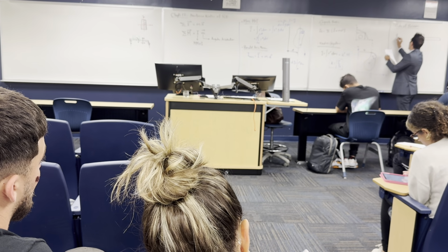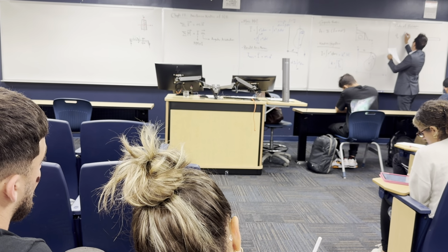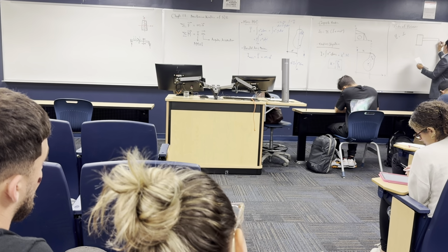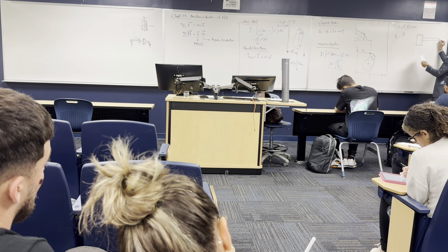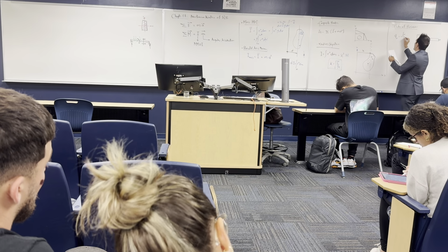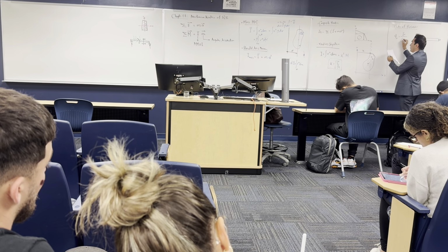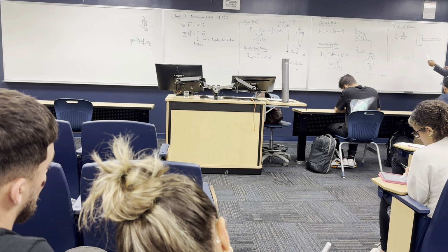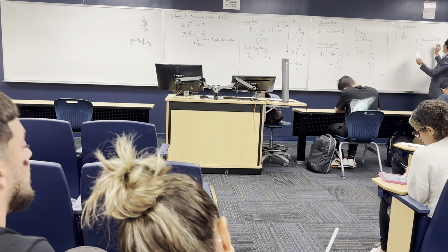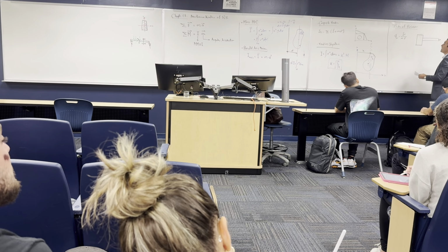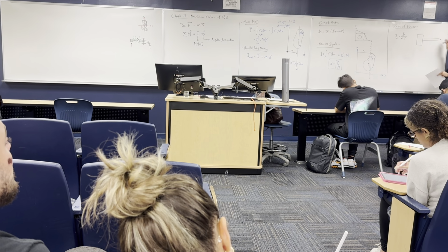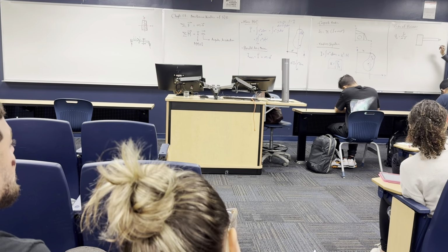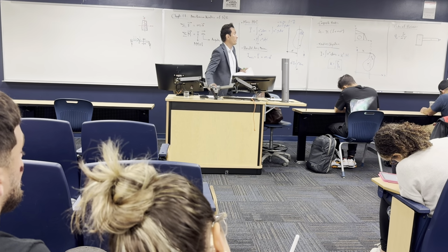The center of percussion, we call it Q node, is equal to the mass moment of inertia about the point, let's say this is the point you are looking at, so about this point, I_O, over the mass multiplied by y bar. Let me tell you what these quantities are. The first thing you need is to find the centroid of the whole body, not only one of them. The centroid of this is here, and the centroid of this is here. So the first thing is to find the centroid of the composite body.